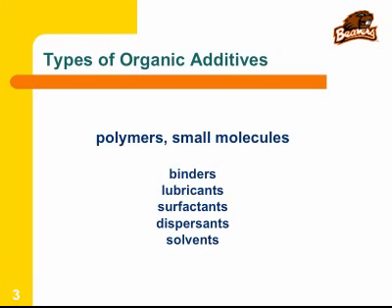When we talk about dispersants, we are also talking about polymers or some kinds of surface adsorption of organic molecules. The main difference is that you want to separate powder particles from each other. You are not so worried about the strength of how the polymer sticks to the surface of the powder. You are more interested in making sure that the powders don't stick to each other. And so the nature of the chemistry changes a little bit.